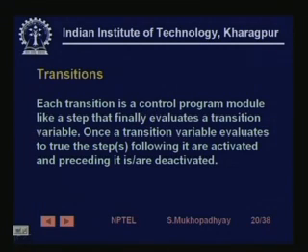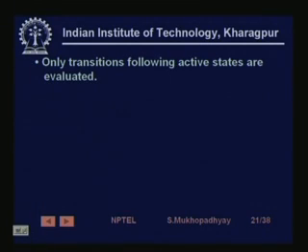But since SFCs support concurrency, it may happen that after one transition two concurrent threads of execution will start. That is why we have said steps following it are activated, and those preceding it are deactivated. Only transitions following active states. So when you are in a state which is active, only certain transitions can occur, so only those transitions need to be evaluated.